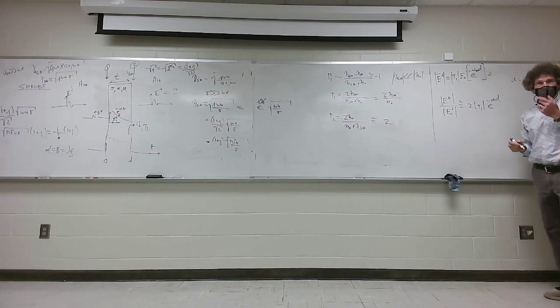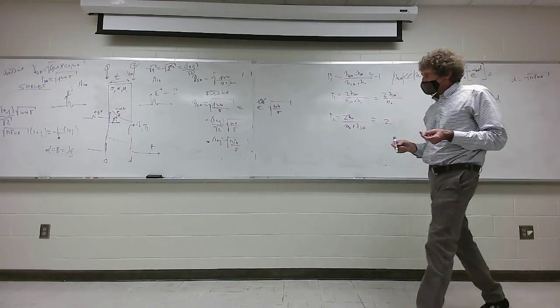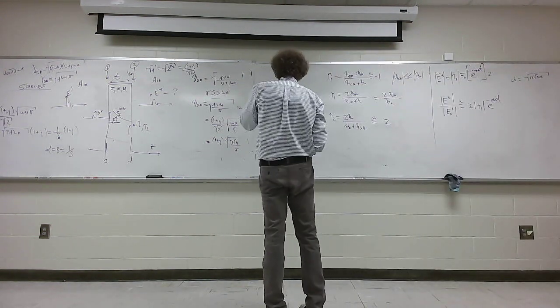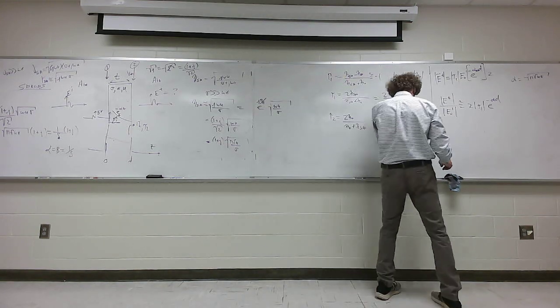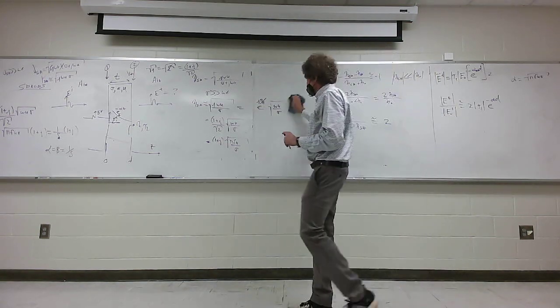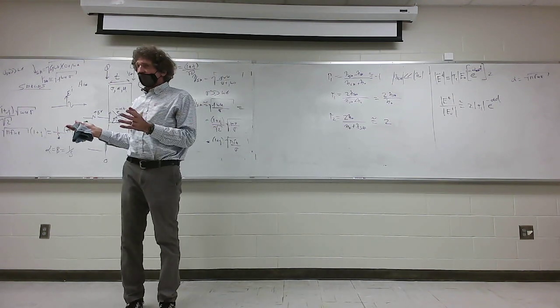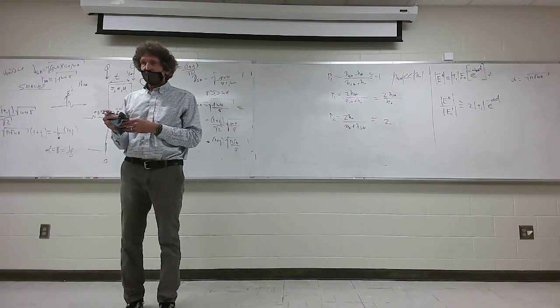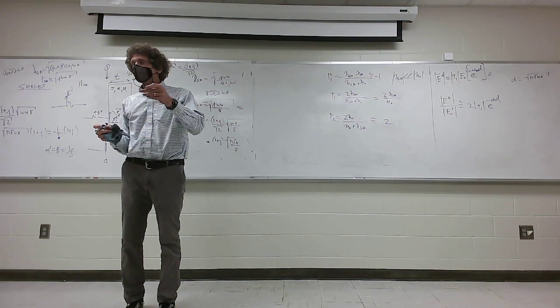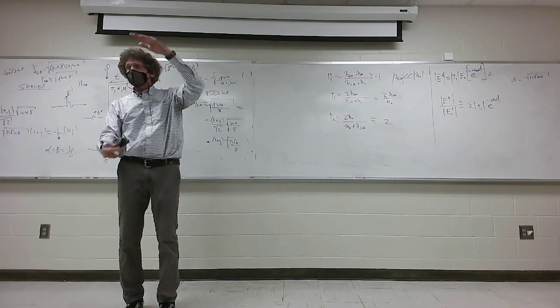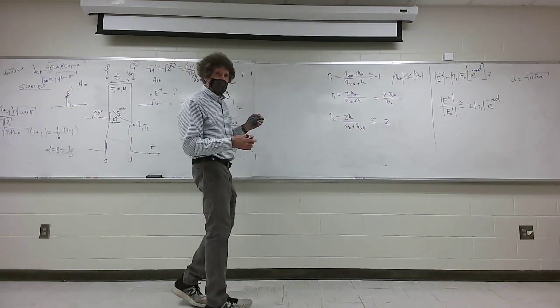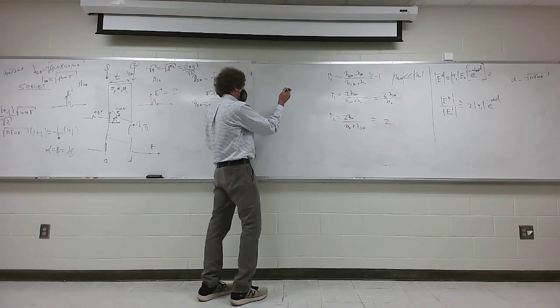But now we talk about something called shielding effectiveness that you've heard before. I'll put it right here. Y'all remember what shielding effectiveness was? Anybody? It's always in dB for starters, right? Shielding is always measured in terms of dB because there's orders and orders of magnitude, so dynamic ranges are incredibly large.